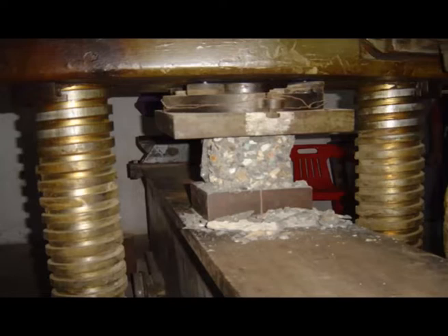That's why this may be classified broadly. One is serviceability in respect of deflection. Mainly we consider, for example, a beam's deflection at the midpoint. Similarly, the cracks, if loaded in a simply supported beam given vertically. Then the limit state of failure in resistance to flexure, torsion or combined effect. So failure can be due not only to flexure.